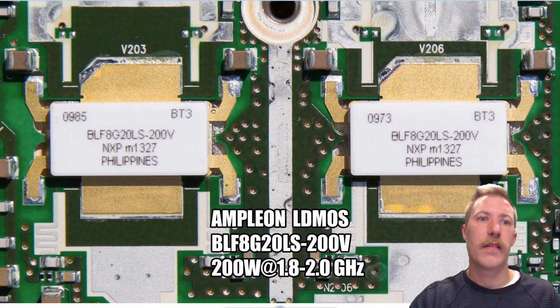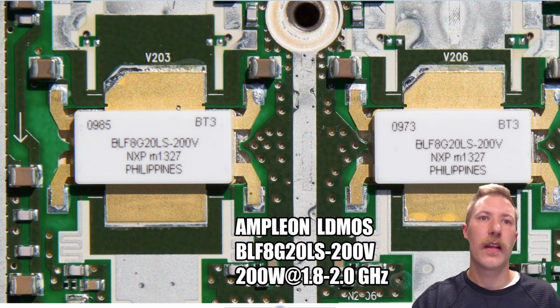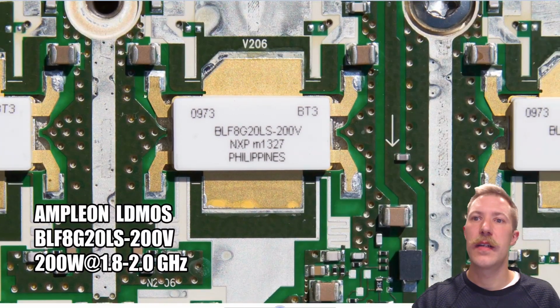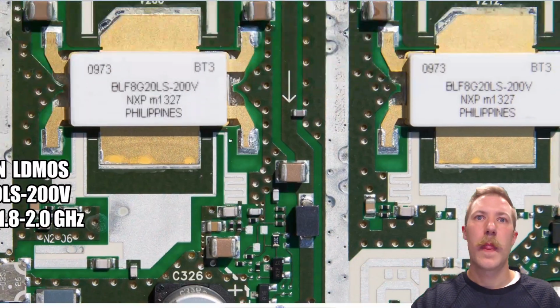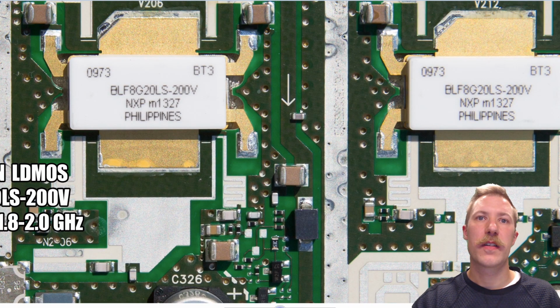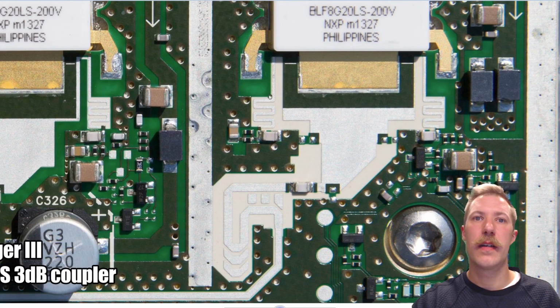But as we can see here, each output transistor has again a lot of decoupling, heavy traces, and we will see a lot of long signal path, so we ensure there's probably a quarter or half wavelength signal path on the power supply rails to avoid any noise injection, which we can also see out here in the corners.